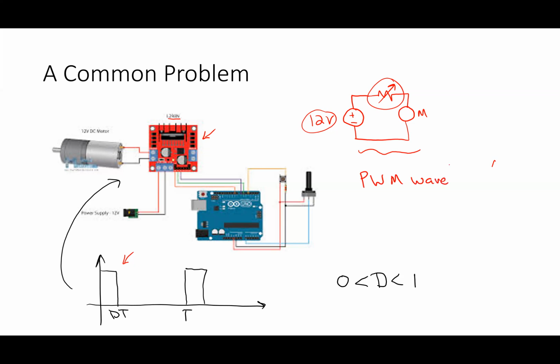So what we do is, it's a square wave that has a fixed frequency, and I vary the width of this pulse. This is written kind of crappily here, but this is the letter D. That D is the fraction of a period from 0 to 1. I change D to make this wider or narrower.